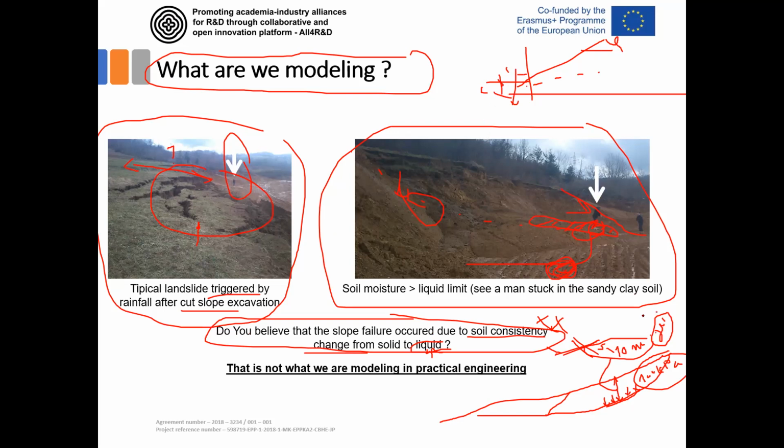But as we said here, there is no liquefaction of the soil when the soil is under surcharge pressure. The liquid can occur only on this free surface where the vertical stress is practically equal to zero, or maybe in the first 10 or 20 centimeters, it can become liquid. So this is just a consequence. What we see here is a consequence of some surface erosion where the soil has become liquid.